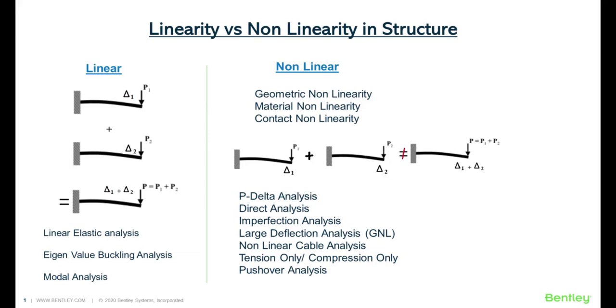You can find more details on this linear response and the nonlinear response through different community posts, and I also have some postings on the Bentley community site where you can find a detailed discussion on this topic. So to summarize, if the structure is behaving nonlinearly, then you need to use the repeat load.